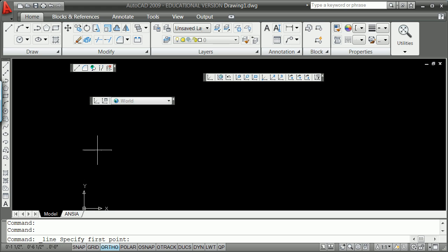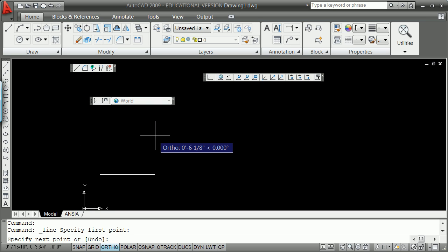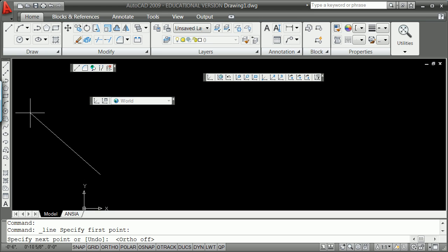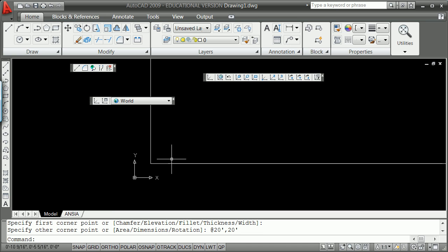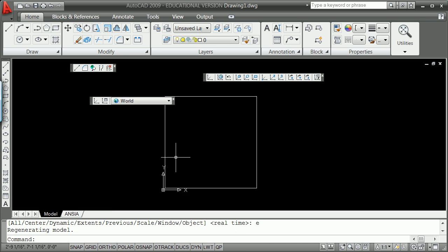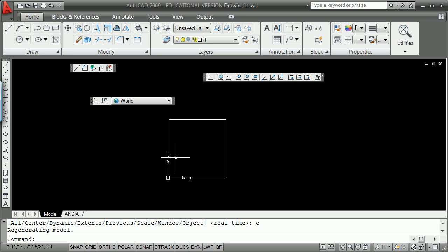And I'm going to real quick just draft up here, turning off F8. This is just drafting a rectangle, hitting escape, escape, escape. Rectangle. I'm going to go here at 20 feet by 20 feet. We'll call it a ravine there. And I'm going to zoom extents, and I'm going to click on this.